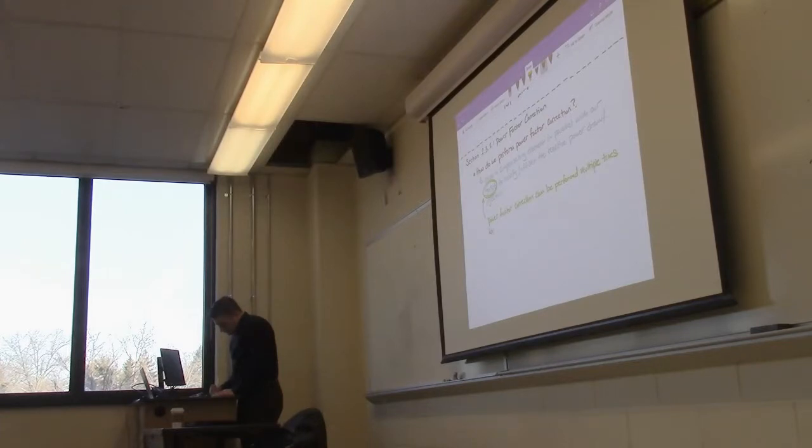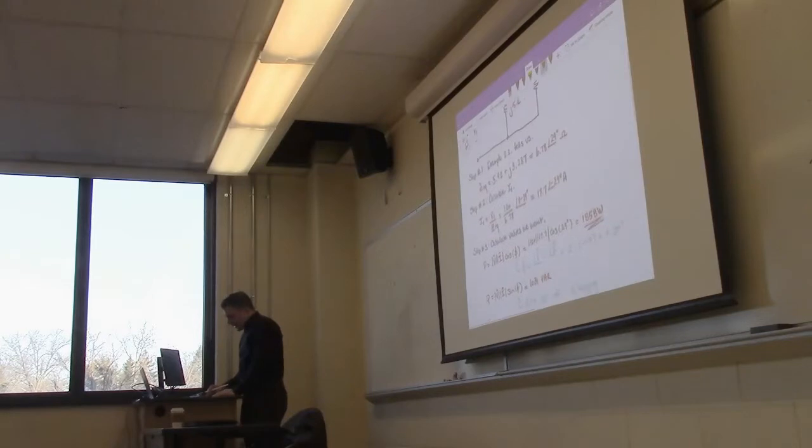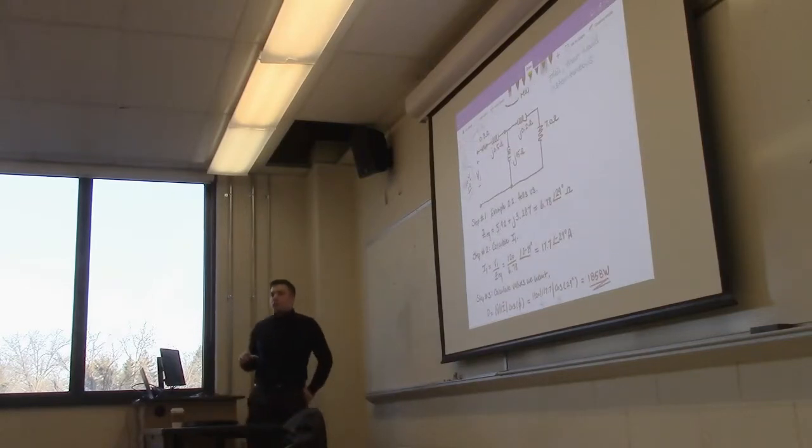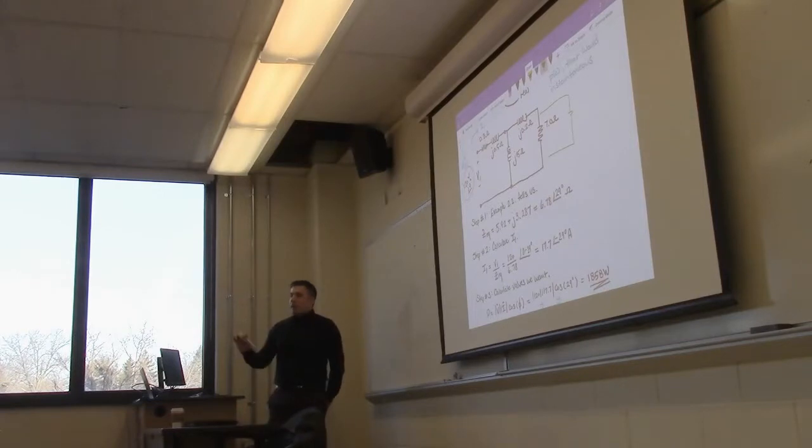You always do it in parallel though? Well, we'll talk about that in a second. If you go back up to this system we have right here, if our goal is to perform power factor correction and our target is the generator or the source, then we would need to place a parallel element right here. Okay? However, if our goal was to perform power factor correction for the load, then we would put an element right here.